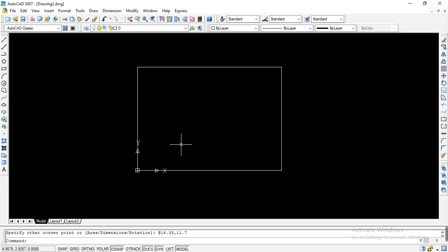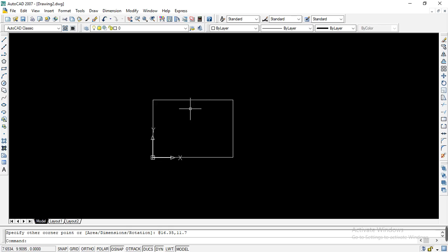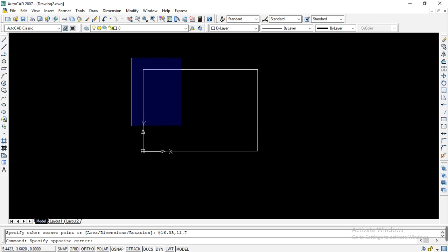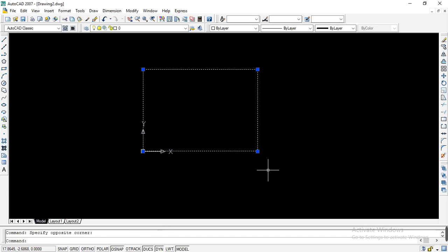So what I'll do next is selecting this object, and then I'm going to offset it. So as to offset it, as I told you before, I have to select it first. Since it is an external wall to be copied, what I have to do is use a thickness from the interval 15 centimeter to 20 centimeter, as the EBCS code recommends.